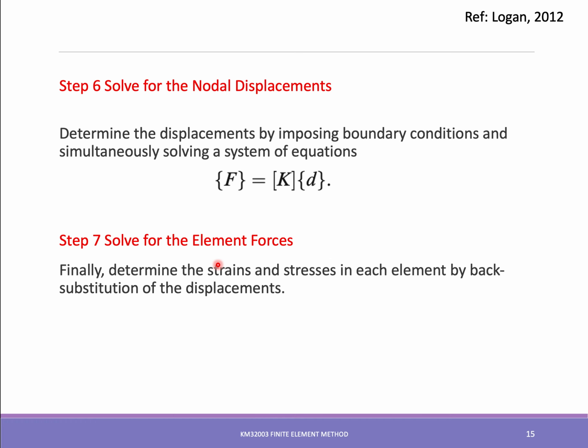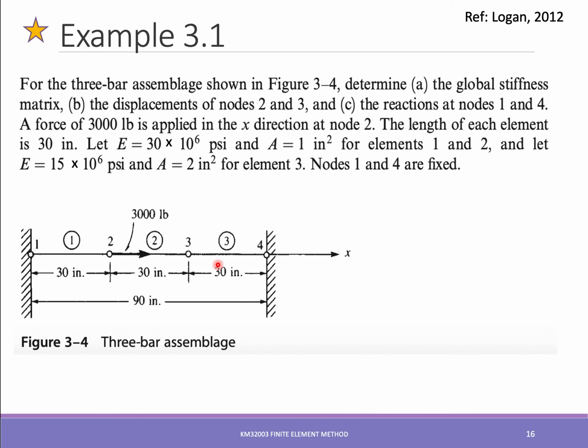All right, so the method, or the concept, is exactly the same as the spring stiffness method. Since they are the same, remember that in the previous lessons we mentioned the direct stiffness method. You can use the direct stiffness method to assemble the stiffness matrix, so it is applicable over here. Let's quickly go through this Example 3.1.